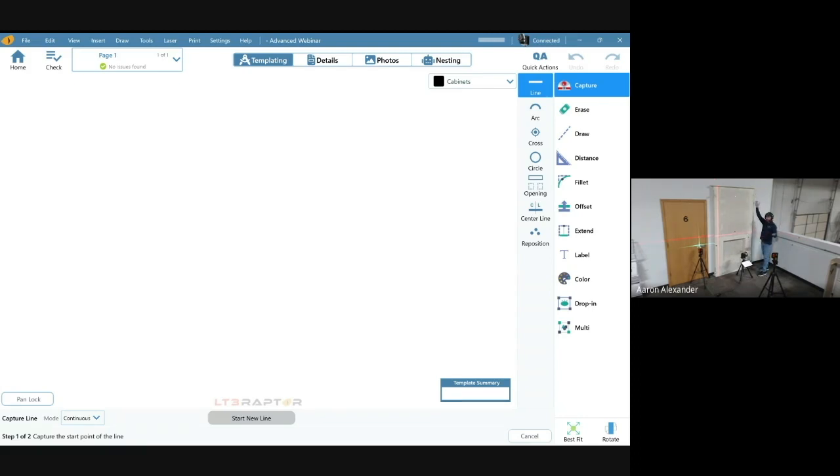So what we could do is set up in the middle. If it's a fireplace that's not too tall, I can stick some targets up on the sides. Now, obviously, if we're dealing with something that's going up 2 stories, what we're going to do in that situation is use reposition. So we could set up our laser out here on the side, shoot the whole left side, right side, firebox, these kinds of things. Then we could reposition our laser to the other side and then shoot and even scribe up the outside edges of this without any targets. In this situation, it's a smaller fireplace, so I just have some targets taped up to the side here to shoot.